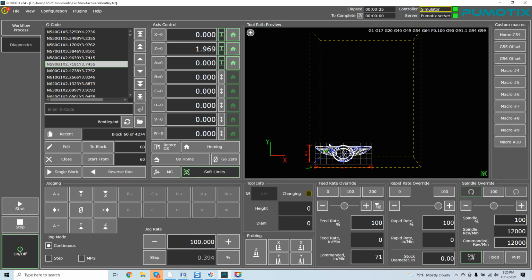But you can see everything here. And the software will control the soft zone as far as how fast you can see the spindle is moving. And overall, it's all about the software controlling that speed at which it approaches an endpoint. You will not have to correlate anything else. So right now, your soft limits are enabled.